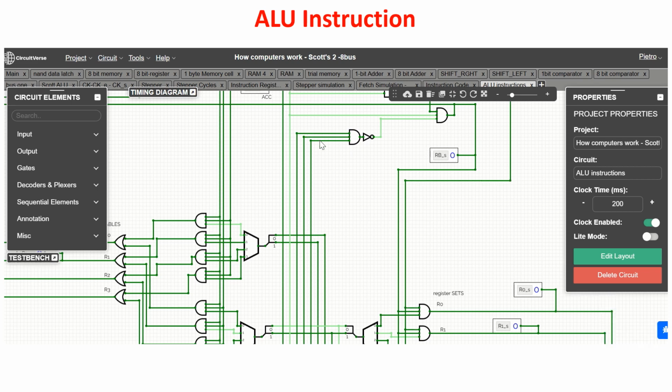When these are 1, 1, 1, the opcode, the AND gate is high, so the output of the NOT gate is at 0, blocking this step 6, because when the opcode is 111 it is a compare operation, which doesn't need any storing in the register B, so it doesn't need the acquisition of a byte in a register.